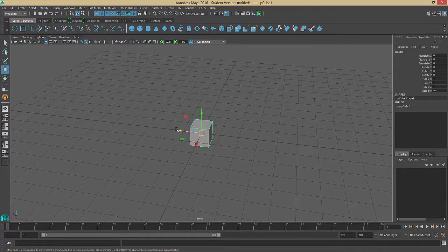Now it's important to note that you want to make sure that you're moving in the proper axes. So if you look at your compass, XYZ, you can see that your Move tool is also color-coded: X is red, Z is blue, and Y is green. So if I grab that arrow, I am just moving in that particular axis. You'll notice that Y is changing over to the right side. I can just click over here and type in 0 to put it back, which is why having this zeroed out as its default position is a good idea, because it's easy to remember the zeros.